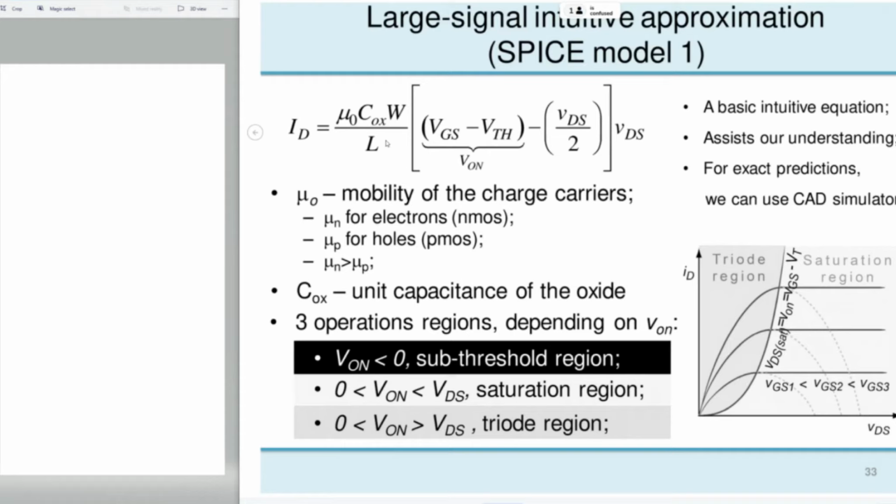So often in jargon among engineers, we say PMOS transistors are slower. They're not fundamentally slower because the mobility of the holes is lower, but they're slower because they have more parasitic capacitance, and more parasitic capacitance means that the time constants are longer. This means that to charge and discharge the nodes around the PMOS transistors usually takes a little bit more time than for NMOS transistors.